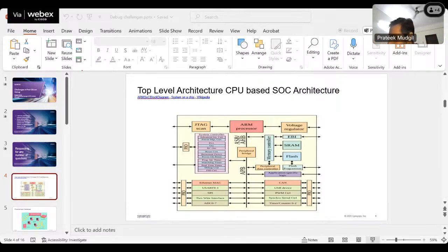You see that the trace length of your data bus, even though we keep them very near, we are working on nanometers and nanoseconds, right? So these trace lengths are different, right? Our data is source synchronous, because our data is synchronous to the source, right? But when it is received, it is skewed. It is received like this. So a lot of skew is there, right?